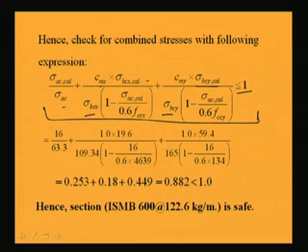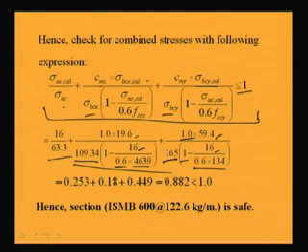So if I put in the values, this will become 16 by 63.3, plus 1 into 19.6 by 109.34, which is sigma BCX, into (1 minus 16 by 0.6 into 4639), plus CMY, also taken as 1 as it is given, and sigma BCY calculated as 59.4, and sigma BCY is the permissible stress, which is 165 because the bending is about the minor axis, and then (1 minus 16 by 0.6 into 134), where 134 is the FCCY value.